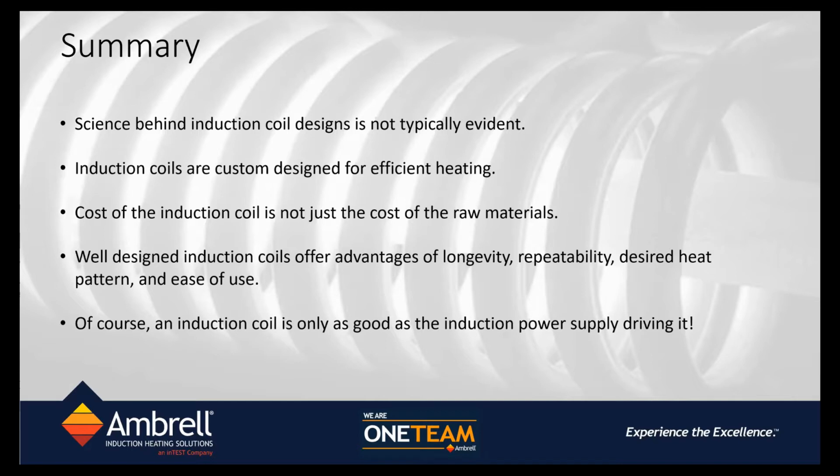Those types of coils have limited life cycles. I have seen coils that have only 5,000 heat cycles on them because they do such an incredible job of delivering high energy in small areas. But then there are coils that we've sold that have run continuously for hundreds and thousands of cycles. So it's actually very subjective as to how long an induction heating coil should run before it burns up, because it's a function of how much power is being put in, how much current is flowing in the coil, how many cycles are being run, and whether there is adequate water cooling available.